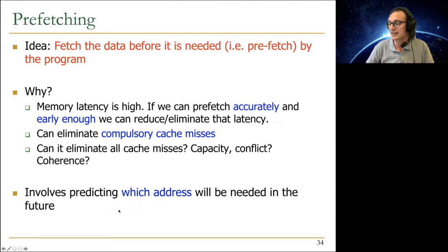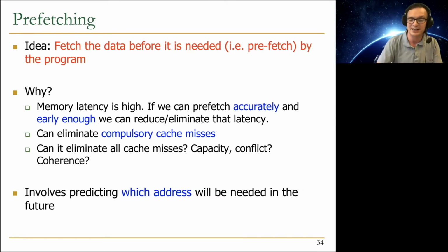So certainly, it can lead to side channel or covert channel attacks that we discussed earlier in lecture 2 or 3, if you remember. And any kind of speculative execution will lead to that, including the speculative execution that we saw using branch prediction and out-of-order execution in modern processors. But that needs to be solved in some other way because it's so important. Prefetching is so important for performance, and it's an important research area right now, today actually, to figure out how to get the performance benefits of all of these mechanisms that require speculation without causing the vulnerabilities that they cause.